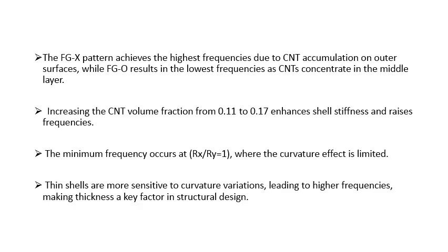The minimum frequency occurs at Rx over Ry equal to 1, where the curvature effect is limited. Thin shells are more sensitive to curvature variation, leading to a higher frequency, making thickness a key factor in structural design.